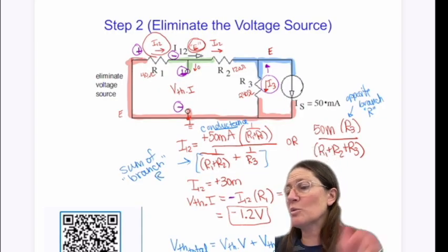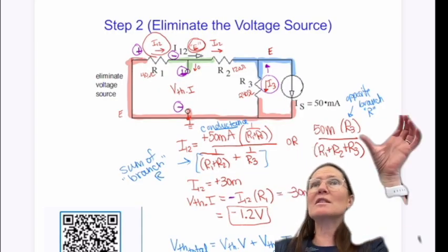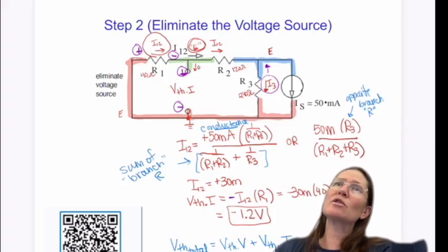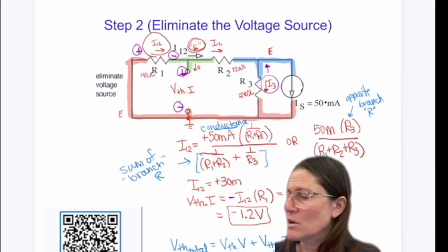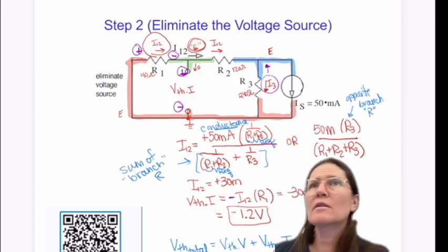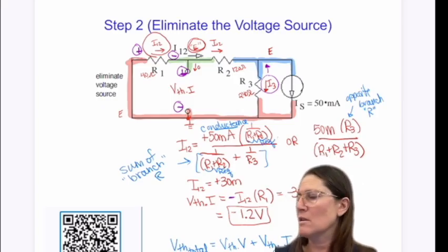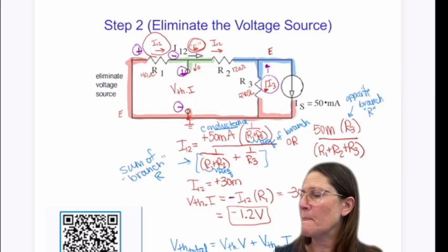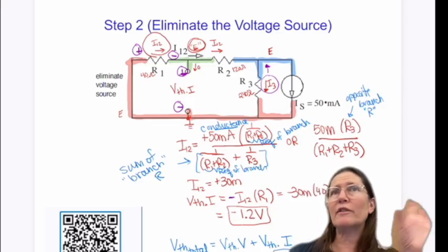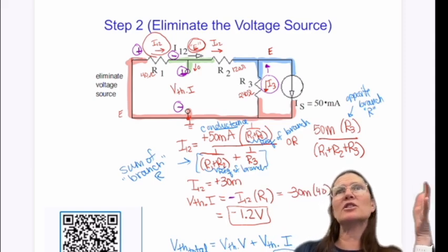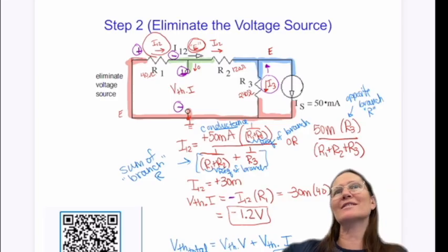So in the case where I12 is, the resistance in that branch is those two in series, so you have to add them together. That's the R equivalent of that branch resistance. Okay, but why are you doing a 1 over that? The conductance is just 1 over. Does that make sense? You have to first combine them as a resistance in the branch, and then you take 1 over each branch resistance.